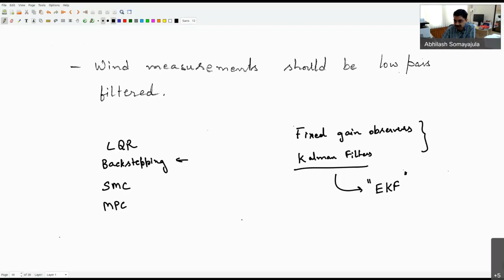So let us say that you have an aircraft where you're looking at a commercial airline autopilot. There, things may be well mannered. You can probably get away with PID controllers for most of the time. But if you're doing flying acrobatics with fighter jets, then you probably will not be able to achieve all that you want to achieve using PID controllers.